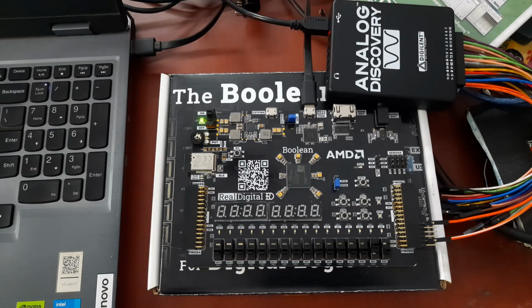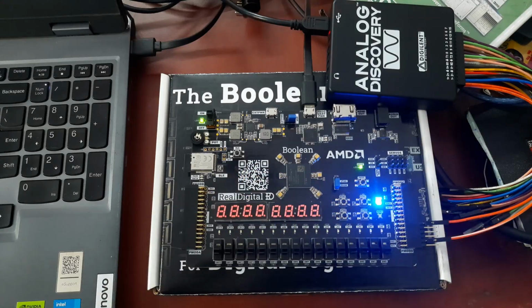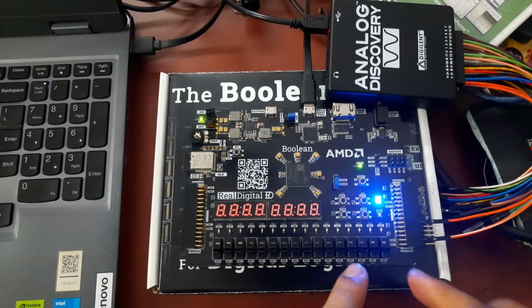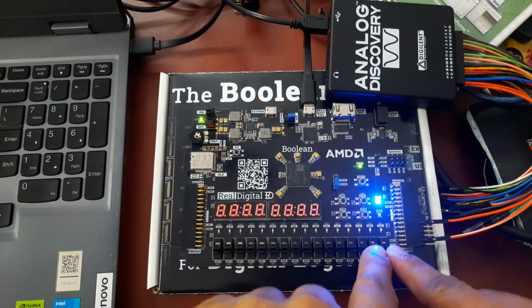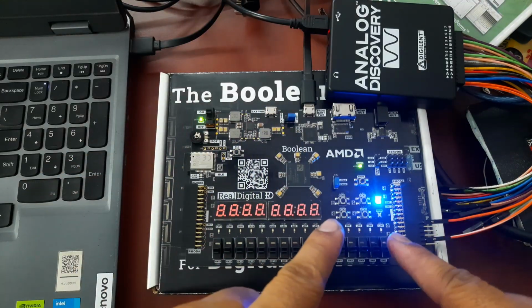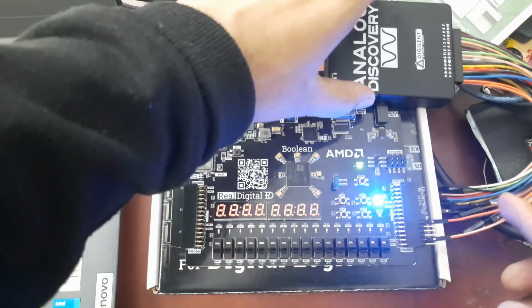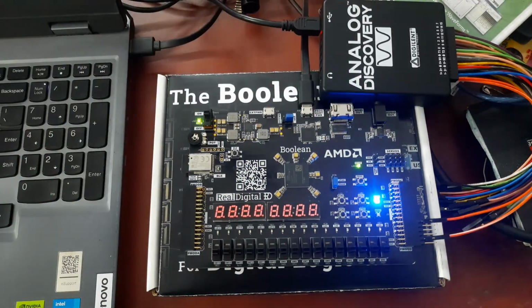Alright, so the bitstream has been generated, and I'll put it on the FPGA and let's program the device. Okay, so right now you can see the LED is on. The switch position is 0 0, so we should be basically getting a full DC signal to our LED. I have also hooked this Analog Discovery probe here, and we'll see it in the waveform software.